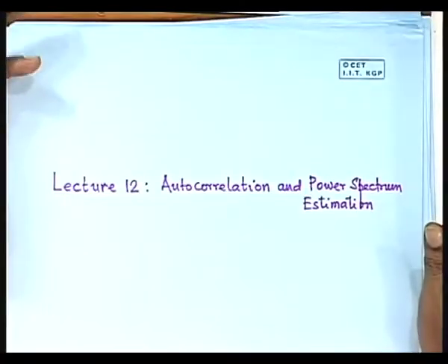And it turns out that under certain rather mild conditions, a lot of power spectra can actually be modeled using linear pole zero models. So, with that we studied the autocorrelation and power spectrum estimation. We studied two approaches, one based on smoothing, another based on ensemble averaging, and we found out also nicely that if we are given a sequence, then these two approaches are roughly equivalent in the sense that they lead to the same kind of loss of frequency domain or time domain accuracies.